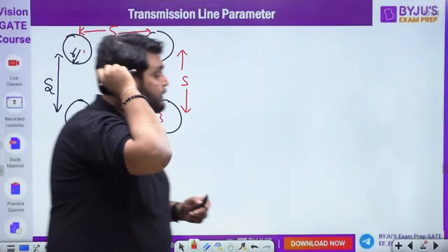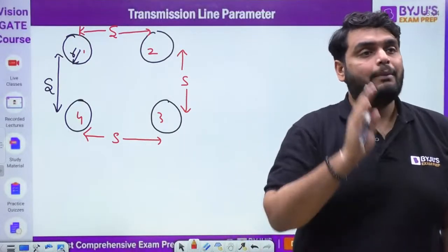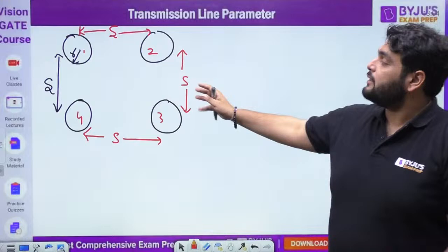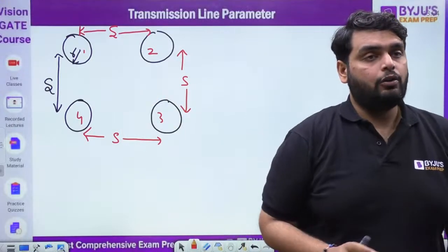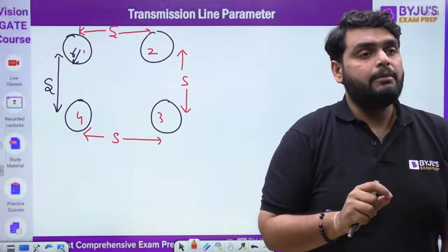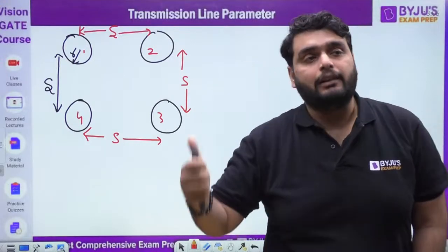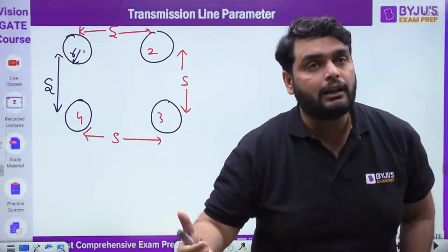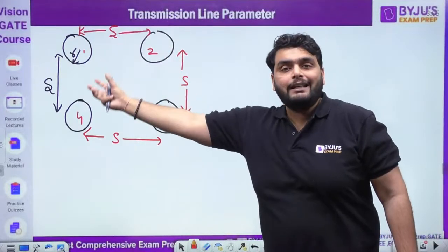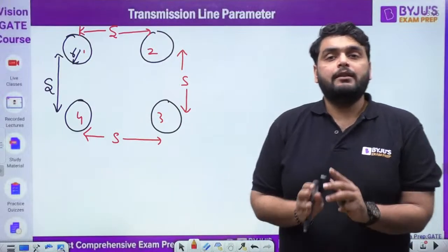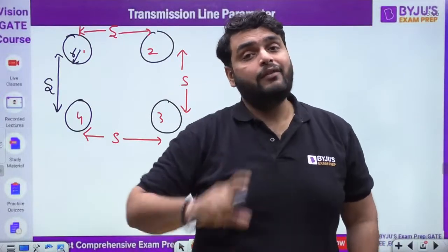Okay, the name of a subconductor. Now, how to calculate the self GMD? Whenever you have a symmetrical configuration, for example, in this case, the self GMD of the entire bundle conductor is equal to the GMR of a single conductor. You can choose any single conductor here, find its GMR, and that will be the self GMD of the entire bundle conductor. This is very, very important.